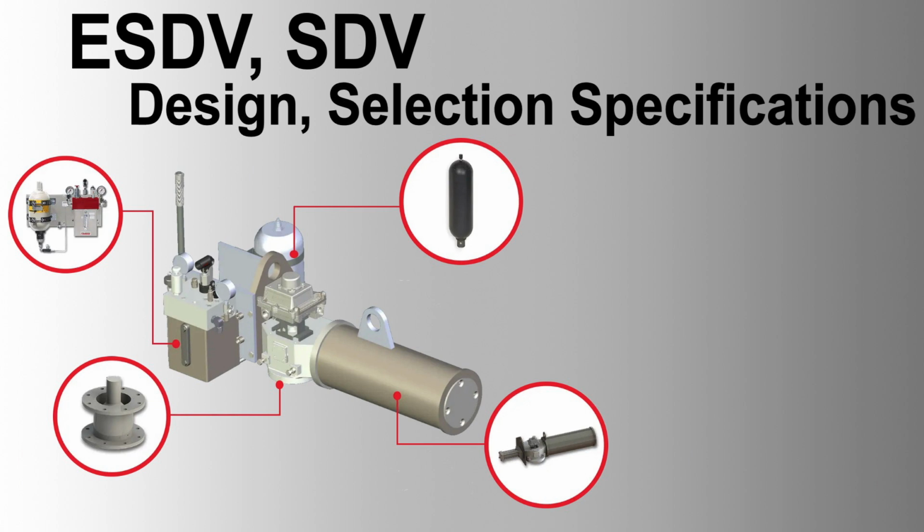Inspection Test Plan, ITP: supplier must include an ITP listing all proposed inspections and tests. Contractor has the right to witness any manufacturing inspection or test. Testing includes dimensional checks, actuator testing, hydrostatic testing on valve and actuator, full functional FAT, and partial stroke function testing. Test equipment must be calibrated and certified.